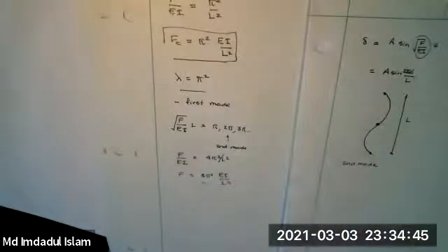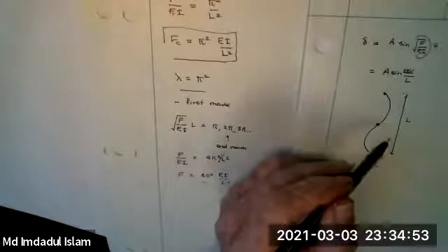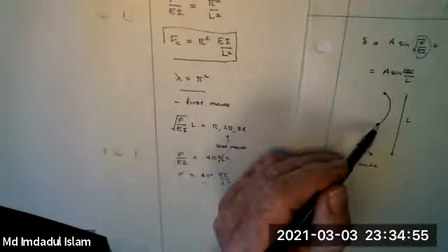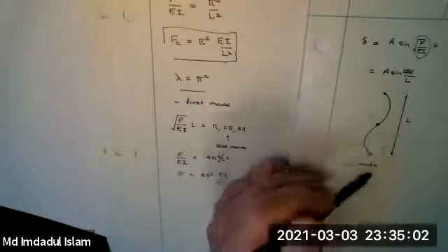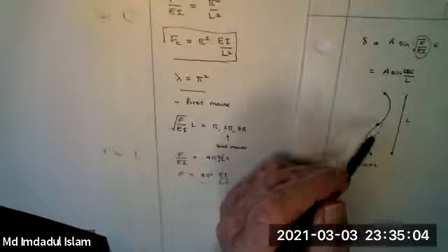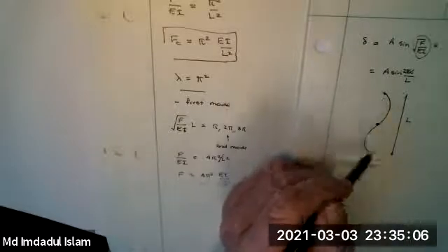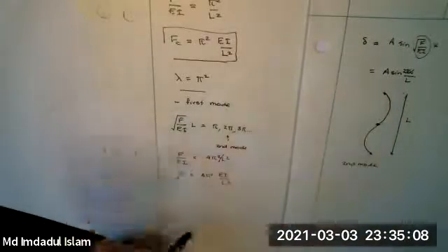I've done this in consulting cases when people have large vibration noises and they didn't like the thing wobbling backwards and forwards. You go up and you clamp the middle of it, even just with your hand, and you change the frequency by a factor of 4. So the noise will probably be out of the audible range. This is a standard trick in engineering to push it into a higher mode.